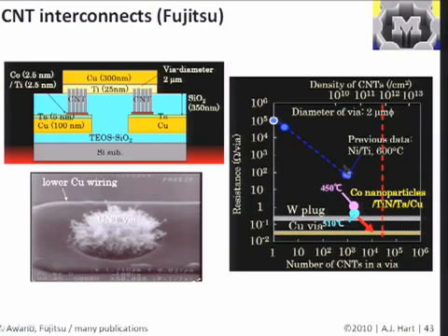Another interesting thing to me is that here they're talking about the same process, using these cobalt nanoparticles and growing them. As you can see, with a growth temperature of 450 C the resistance is somewhat higher than at 510 C. It's actually quite a substantial difference, a factor of a few, because it's a log plot. A higher growth temperature means you grow nanotubes with lower defects.